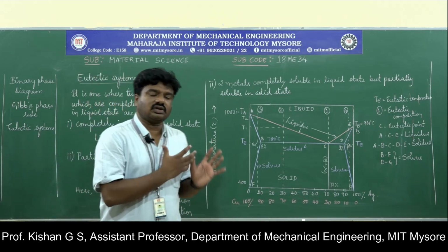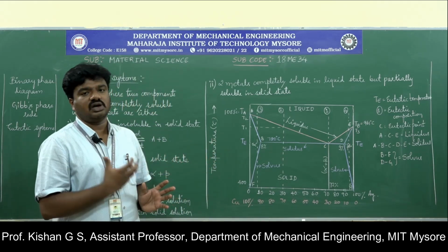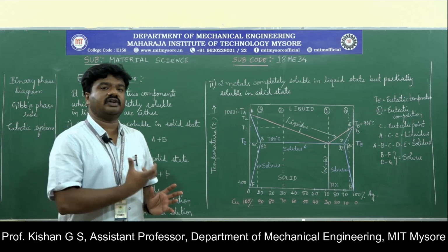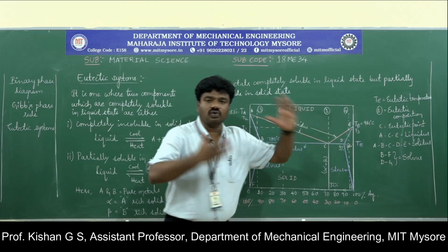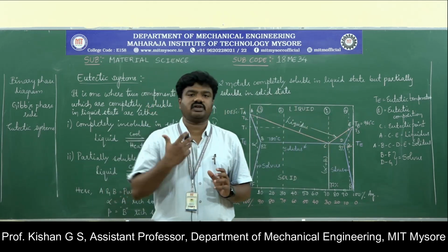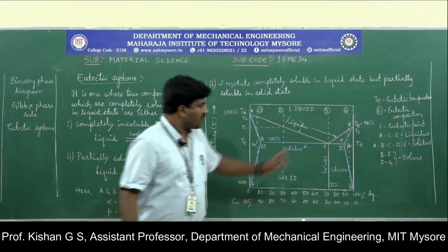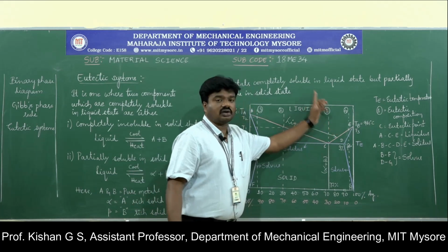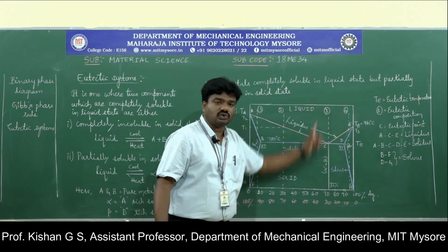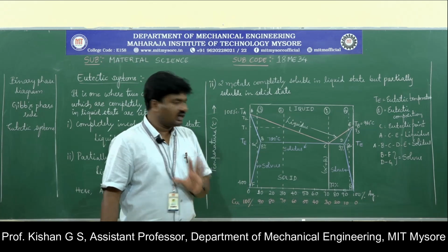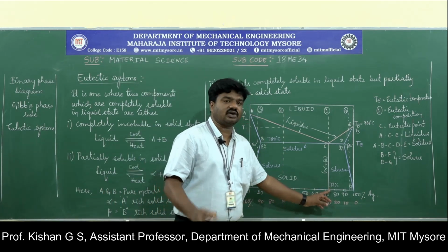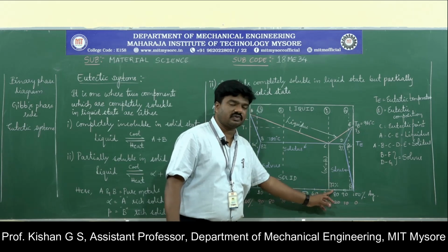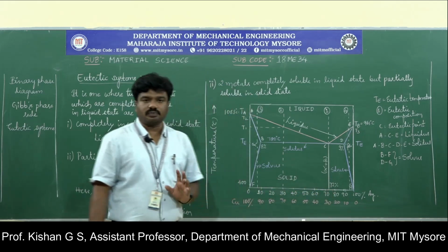The main concept of understanding this diagram is to assess the behavior of various compositions. Here 1, 2, 3 and 4 are only the points of concentration, or where we are going to check, whereas 1 is always the constant, which represents the eutectic composition only. See, here it is not 70-30, it is the exact eutectic composition: 72% of silver, 28% of copper.